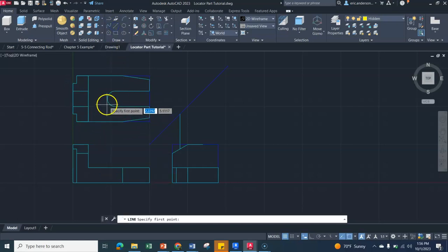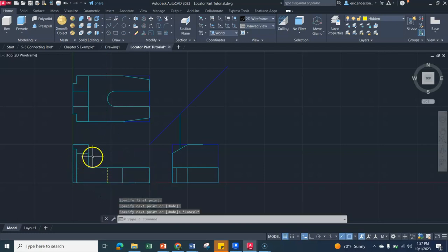So let's grab our line tool. I'm just going to take the edge of that circle, not clicking, and drag down to find my reference point. Come on, AutoCAD. There we go. And it's going to go down. And notice how it's already set up to do those dotted lines, so we actually don't have to mess with that, which I am a big fan of. No hidden lines there. All right, we're looking good.